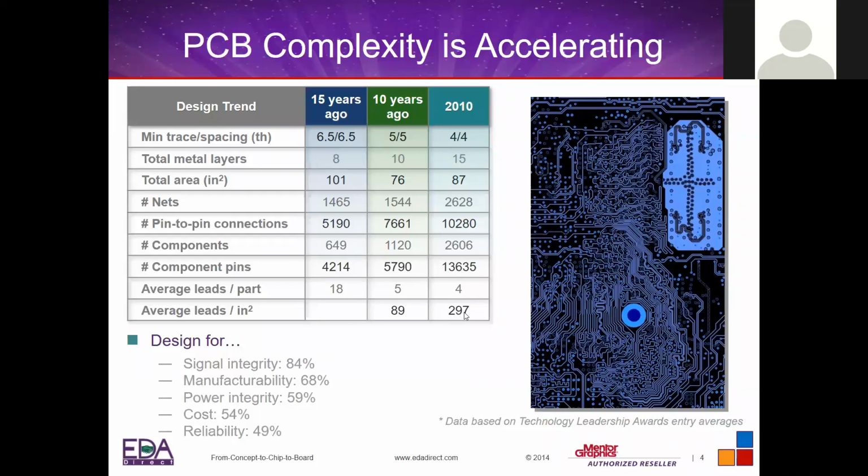All right. So definitely the signal integrity side issues are becoming more of a problem. And also, if you have things like FPGAs on your board, you will have to handle and deal with many power distribution networks: 5 volt, 3.3, 2.5, 1.8, 1.2, 1.1, 1.0. So many of these rails have to be properly designed in order to have good signal quality. So overall, we see an increase in complexity in debugging and manufacturing for designs going forward.